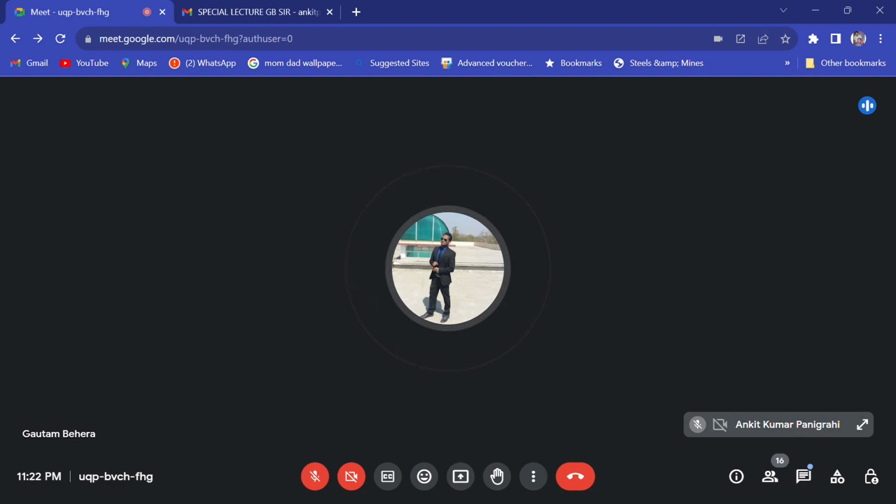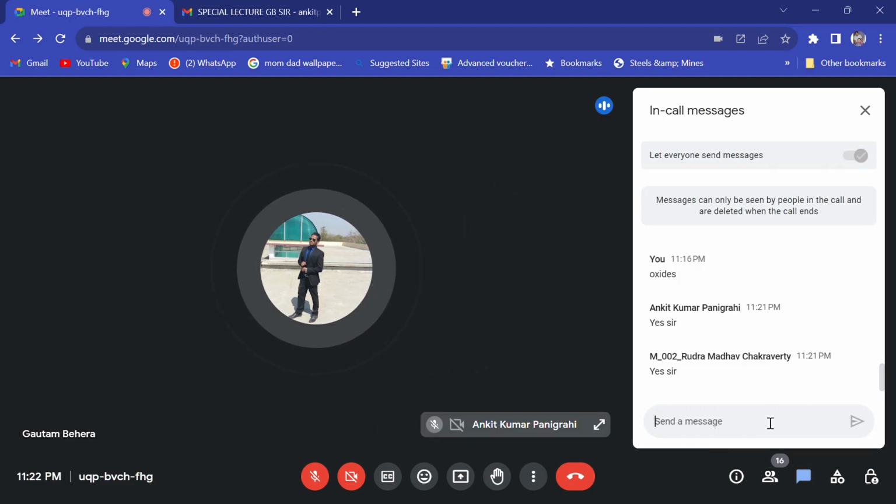you want to make stainless steel out of these raw materials. You have stainless steel scrap, you have mild steel scrap, you have fresh nickel, and you have added high carbon ferrochrome, right? So what can be done? Can you tell me, does stainless steel contain less carbon or high carbon? Let's move to some physical metallurgy, then we'll discuss. You are producing a stainless steel, it should contain high carbon or low carbon? Less carbon. Very good. Why?